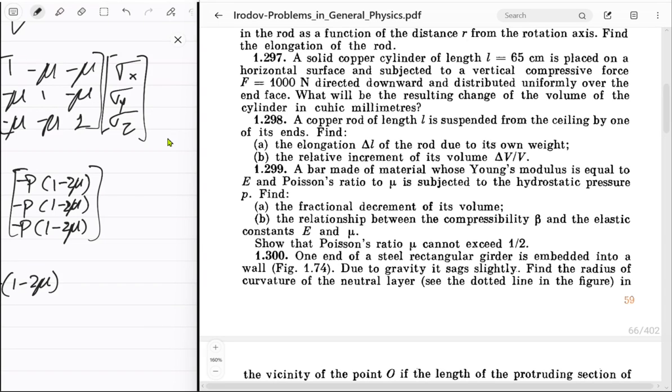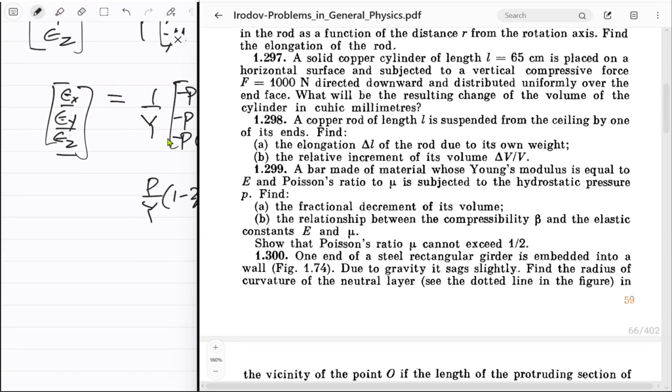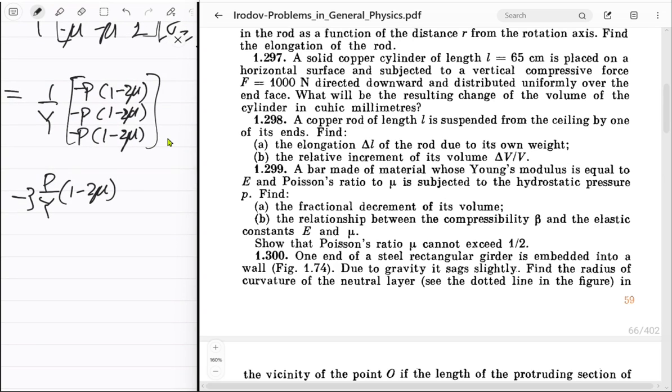So it's tensile stress, but the pressure is actually compressive, so it should be negative P. And that would be the correct thing. Also, these are in fact tensile strains, so no big deal with that. So dV upon V is just equal to -3 of this thing. Of course, that just means the volumetric strain is compressive, which is obvious because pressure is there.